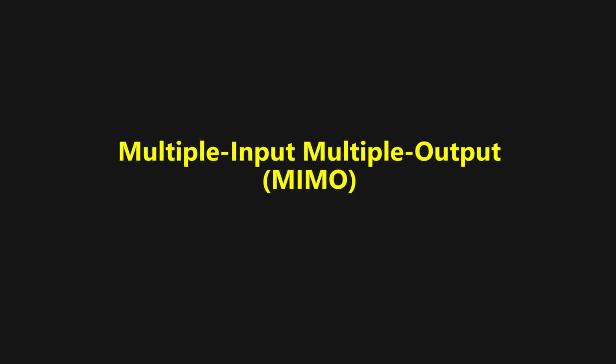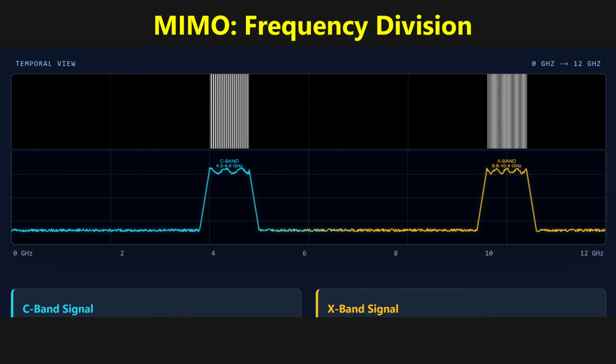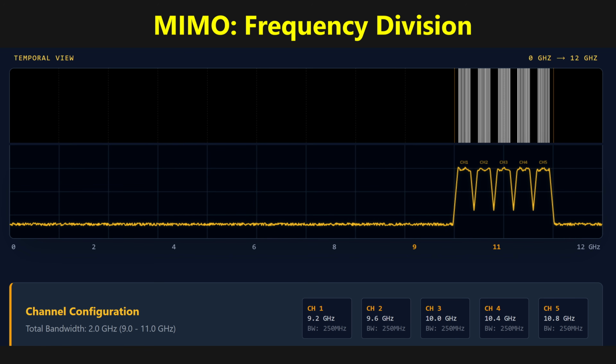A way to directly improve the PRF is with multiple input and multiple output antenna arrays that produce different types of pulses that will not interfere with each other. The simplest way to do this is with frequency division, which means sending chirps in different frequency bands, and the downside of this is that it requires more bandwidth, assuming you keep your range resolution constant. If you sacrifice your range resolution and lower the bandwidth, then you can increase your PRF drastically.